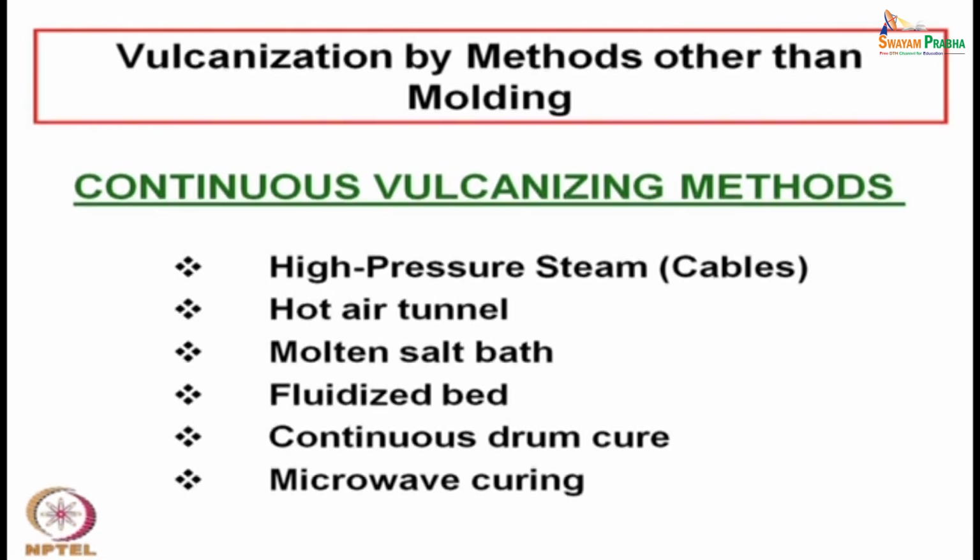Say in the case of cable, the cable is made through an extrusion process, and that passes through a high pressure steam chamber, where the rubber covering of the cable gets cured between entering and going out of the chamber.